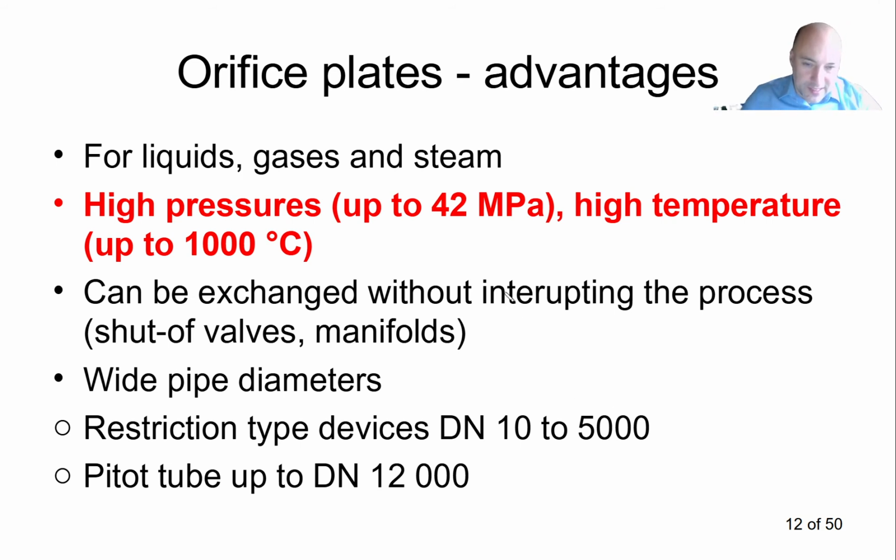So let's summarize the advantages and disadvantages of an orifice plate. So what are the advantages? The orifice plate can be used for all mediums. So it can be used for liquids, for gases, and steam. So all three. This will not be the case, for example, of the ultrasound. We'll see that it will be different.